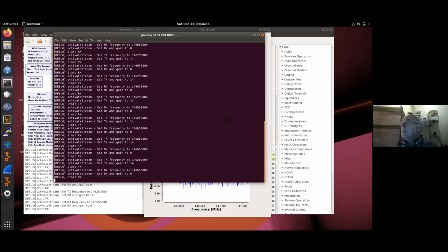There were some lessons learned on building the power amp. I originally had thought that I would just monitor the signal level coming from the HackRF and switch the power amp on automatically. But because it's so low coming out of the HackRF, it was switching over when it wasn't supposed to.